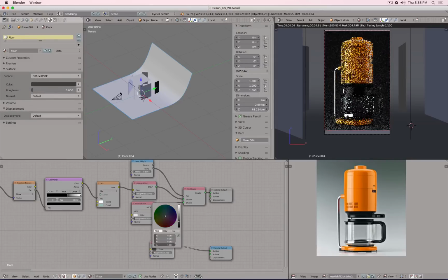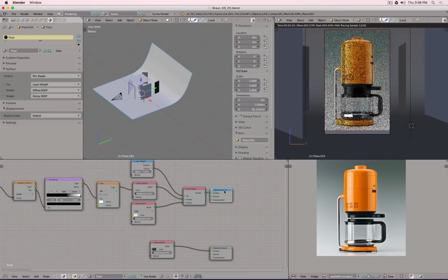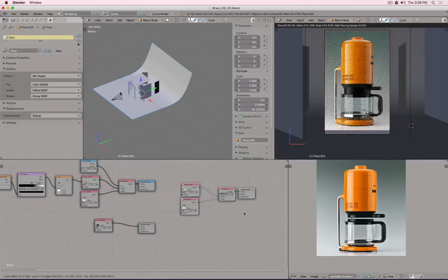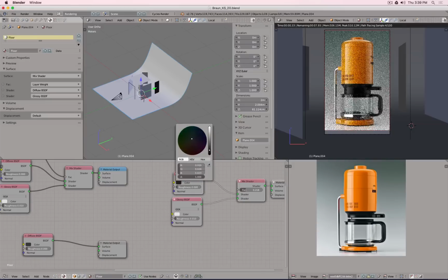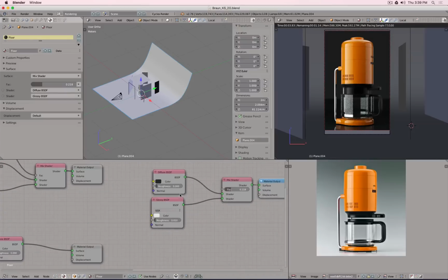We could also lower this color, so for example, make it really dark. And then we have a really nice high contrast, mysterious looking rendering. The only problem is, as you can see, the glass now doesn't really work well, because you need something bright behind the glass for it to show up. But you see, just by adjusting the backdrop colors, you get really nice, interesting results. And for example, we could select these two, Shift D, and let's say this one should be really dark, but I want this glossy reflection.